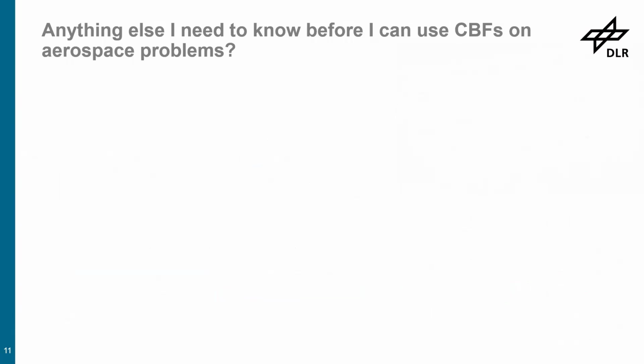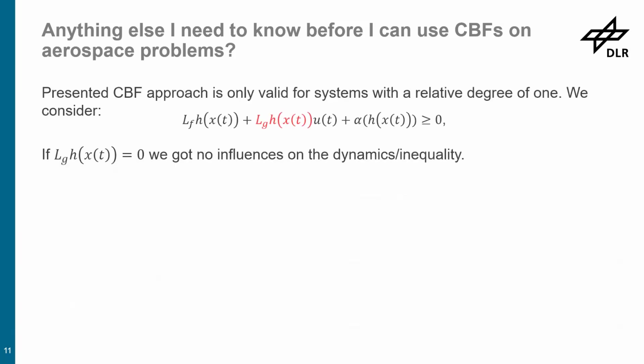But it's just a partial truth, because you will sometimes have the issue that you take the time derivative of the dynamics you're trying to control, and the part where u is acting is 0, right? You could argue it means you don't have any controllability over your safety at that point, right? You can't render the system safe with the control inputs you have available.